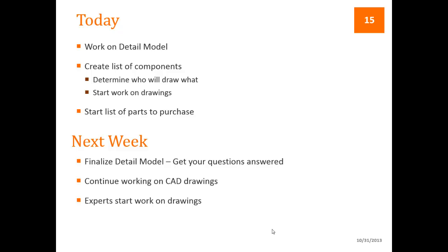Work on creating your list of assemblies, sub-assemblies, and components in your fab plan, and I would recommend each assembly gets its own line, then under that you've got your list of sub-assemblies, and under the sub-assemblies you've got a list of all your components, so that you have space in your fab plan then to indicate what processes are necessary for each of those.